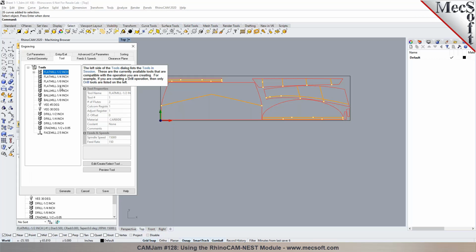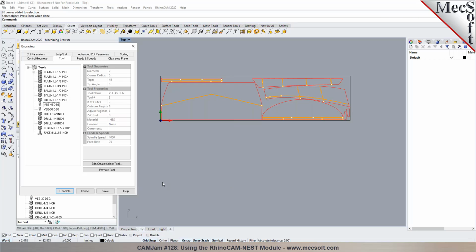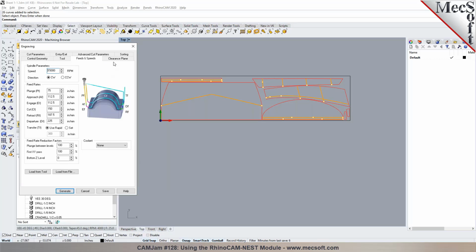Would you want to use like an end mill, like an engraving bit, like a V bit? Or what type of tool would you like to use for it, sir? I think the engraving will be the one to use on that one, isn't it? Okay. So, yep, we can do an engraving, a 45-degree engraver. We'll pick that. And then you can set your feeds and speeds.